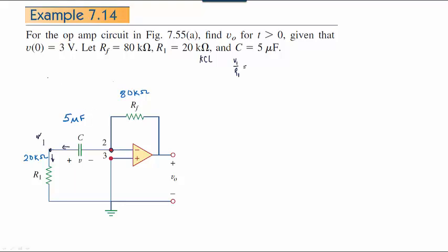But we also know that I in a capacitor is C dV/dt, but it's actually in this case 0 minus this voltage, which is going to make this a negative sign. So it is actually minus C dV/dt. So it's actually 0 minus C dV/dt to get the current, because it's going into the node, so that would have a negative sign associated with it.